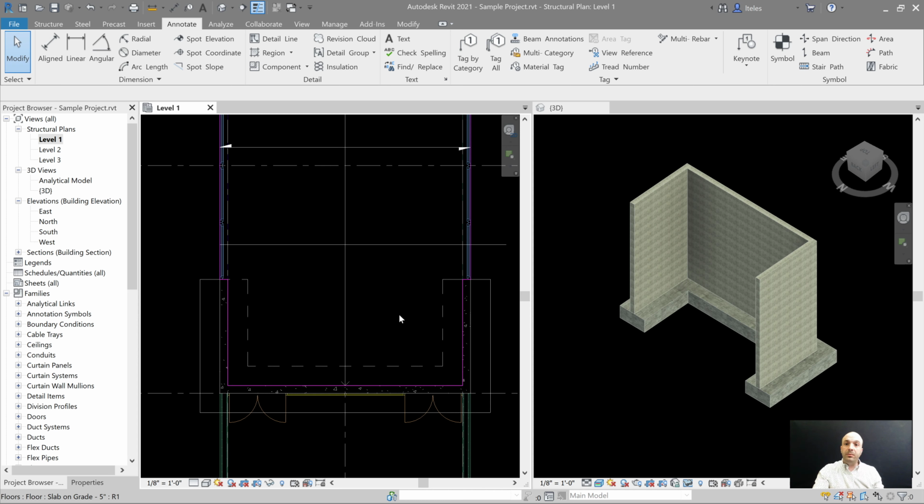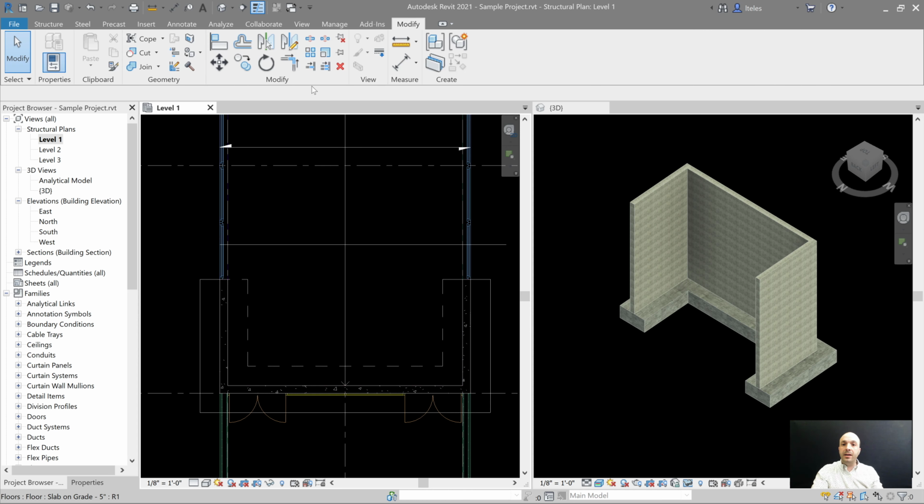And now I can use my trim tool. So modify, trim, extend multiple, and now I can select that line and I can trim these beams over. Okay, and you can see that the 3D updated. All right? So those are just some perks of using beams for foundations. As we keep populating this model, you'll see all the other perks that come with it. But for now, it allows us to have more functionality, more flexibility over our model.